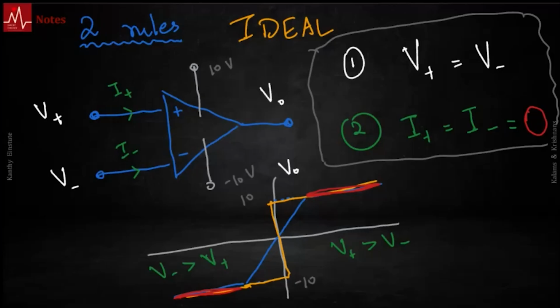Solve the problem. If you are getting a value between 10 and minus 10, you are in the linear range. That's your answer. If you are getting 10 or minus 10, or sometimes higher, you're not in the linear range. Your answer is the saturation voltage. Again, I'll show you two quick examples. Fortunately, we have two PVQs.